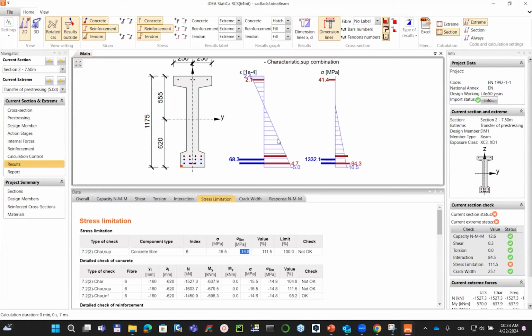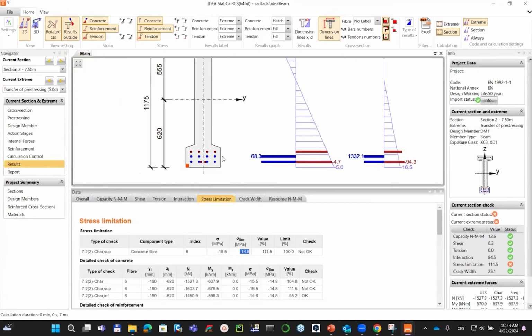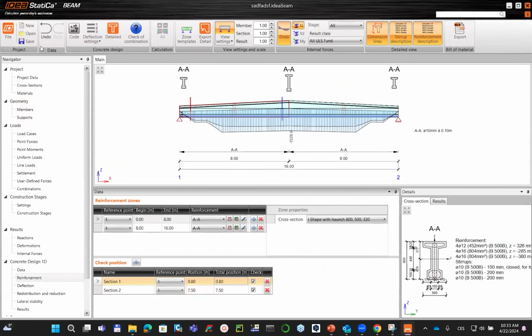C35/45. We can also decrease the anchorage stress, because right now there is 1.4 gigapascal. Or we can put in more reinforcement that will also cover some portion of the stresses. There are more options that can be used because we are 11% over.